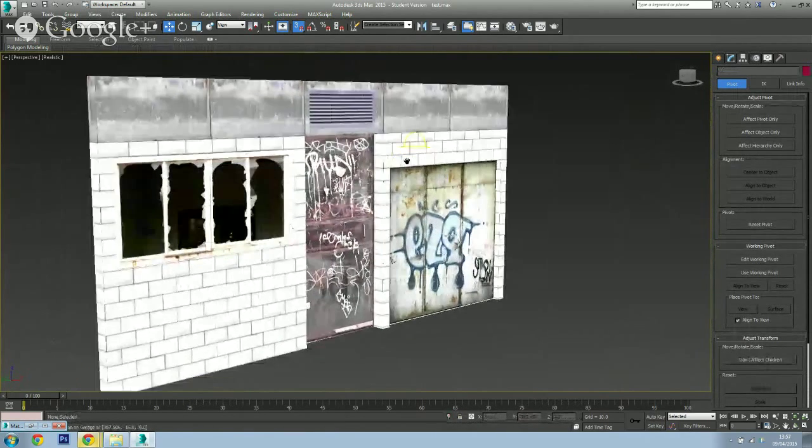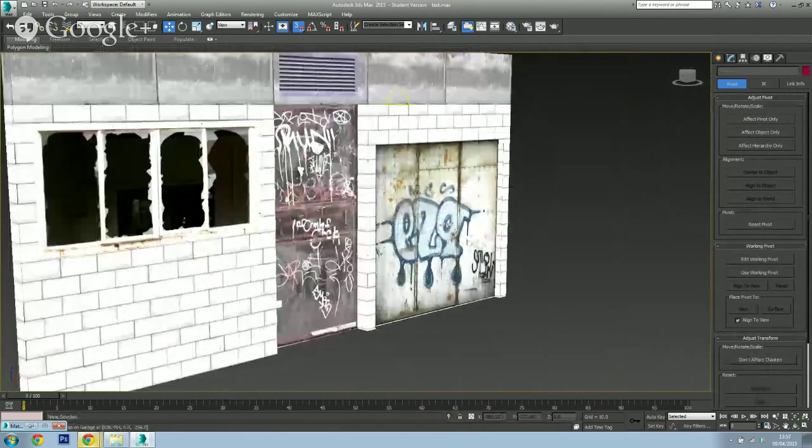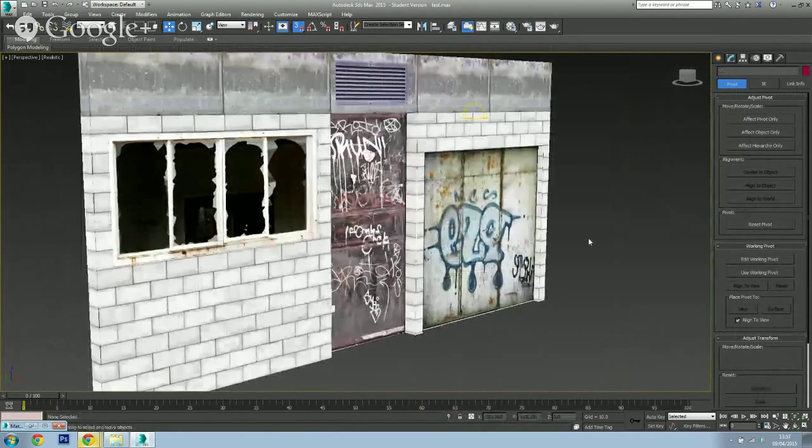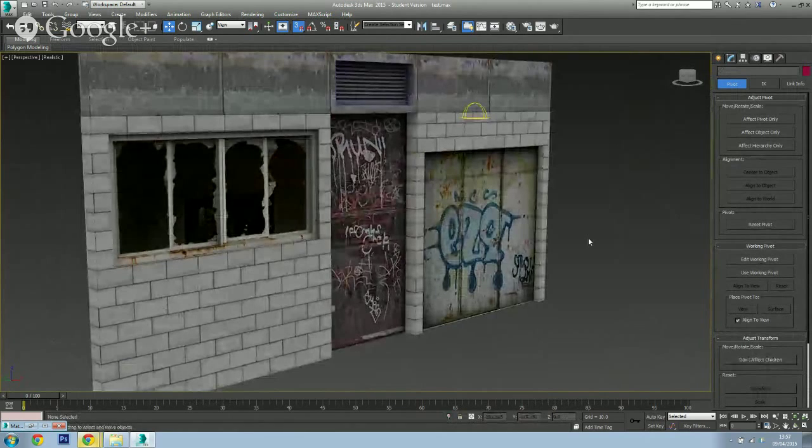So now, in quite short succession, I've managed to create this little scene which has indented windows and garage doors and doorways and all that sort of stuff. And I know that I can reproduce this super quick. I know I can swap out different windows, different doors, whatever I want, because it's all the same size, it's all modularly built, and it's all using a texture atlas. Okay, so that's how we do it. I hope that all makes sense.